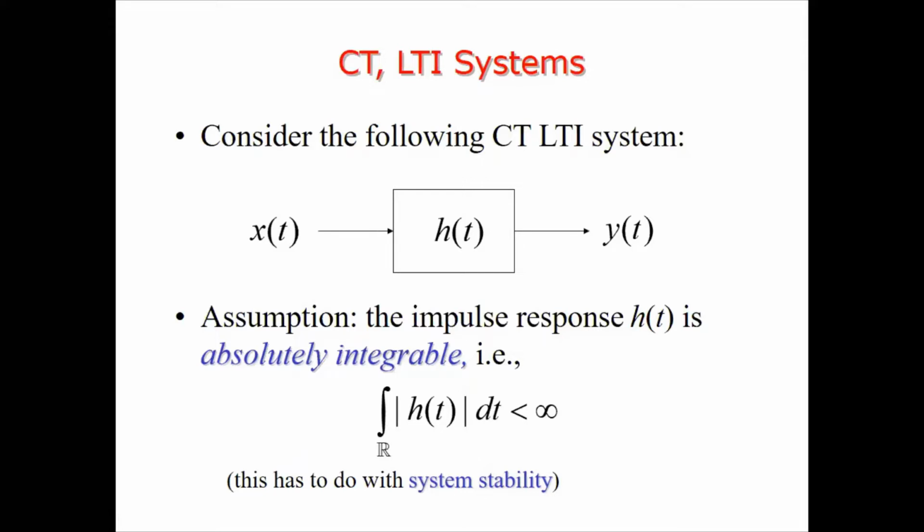Why is it called the impulse response of the system? The transfer function, which we understood as a ratio of Laplace of output by Laplace of input, is also called the impulse response of the system. So what is meant by that? We knew that C of S by R of S equals some transfer function G of S.